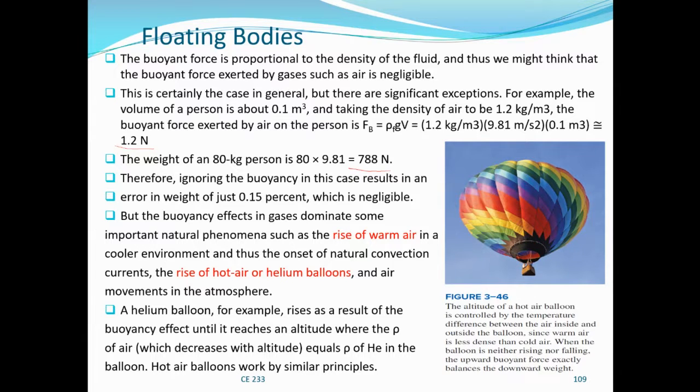Whereas if it were in liquid, you remember the instance when we weighed an object to be 7 pounds in air, but in water it becomes 4 pounds. So the buoyant force constituted almost 45% of the weight. But in air, it is so small that it can be neglected. Buoyancy effects in gases, however, dominate some important natural phenomena.